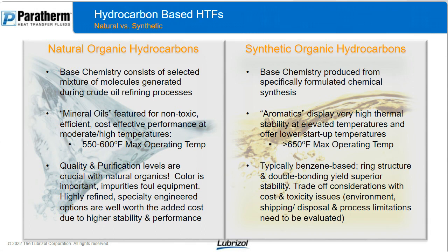They're usually non-toxic. They're very efficient, cost-effective performance, but the maximum operating temperature is really limited to usually somewhere between 500 and 600 degrees Fahrenheit. So if you're operating at or above those limits, you're going to probably want to consider something a little bit more robust in a synthetic product.